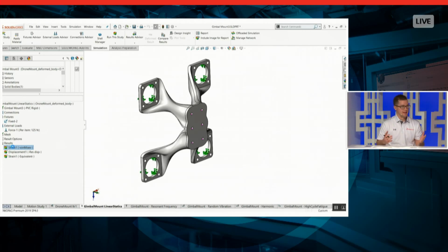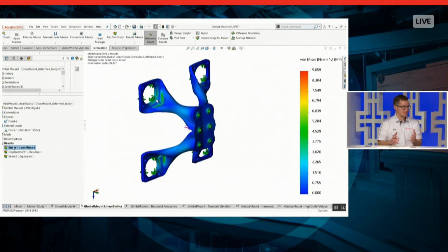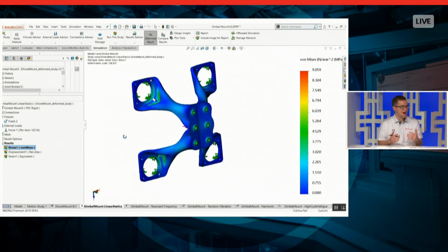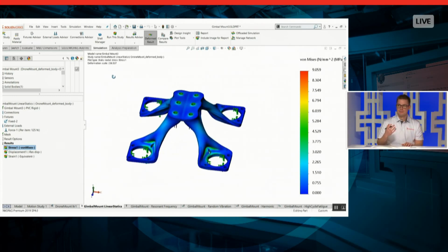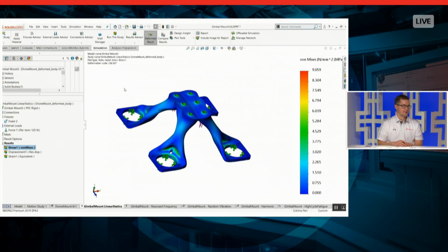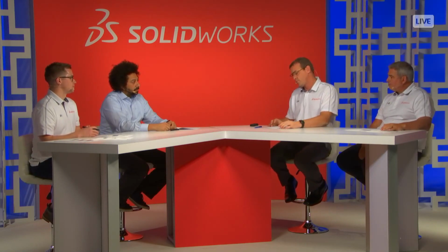So if we're going to casting or wherever it may be. And then, of course, to get the warm fuzzies, if you will, of being confident in your design with that shape created inside SolidWorks, we can run one more simulation study, get the stress, get the displacement, make sure we're where we want to be. So, 3 really different ways to leverage simulation when we think about creating parts, checking parts, determining if they're going to be in those right places.